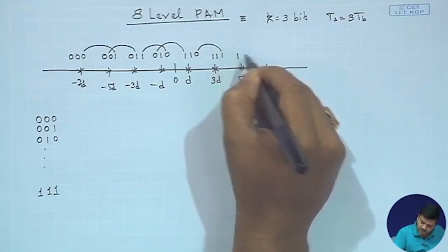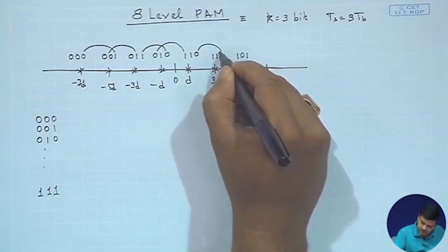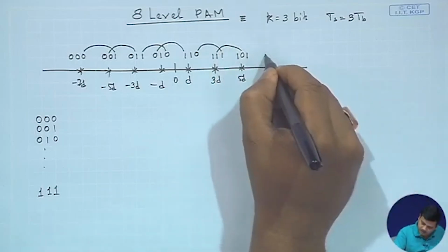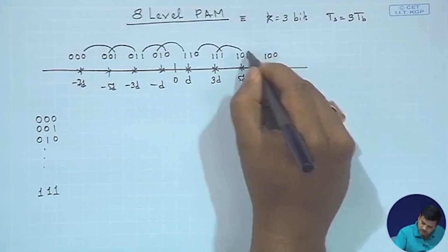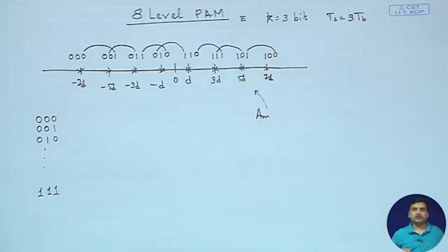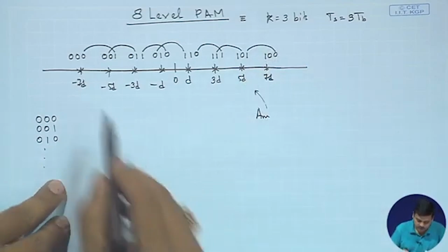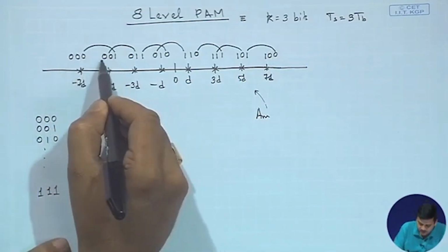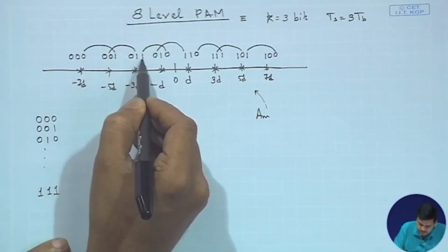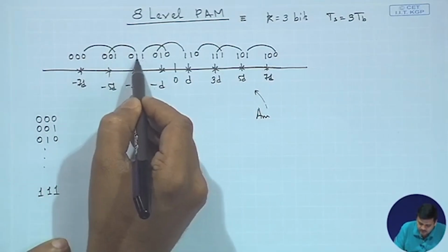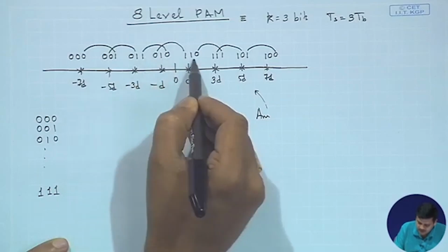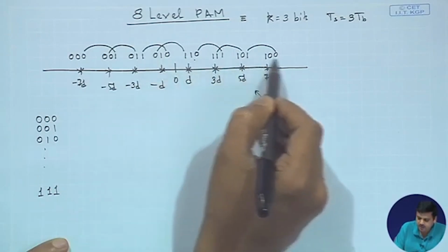Then we could say 1 1 and 0, make this, and then you could have 1 0 0, you modified this bit. So, in this way what we see is that these two neighbors differ only by 1 bit, this and this neighbor differ only by 1 bit in the middle bit, this and this differ only in the extreme right bit, this and this in the extreme left bit, and so on and so forth.